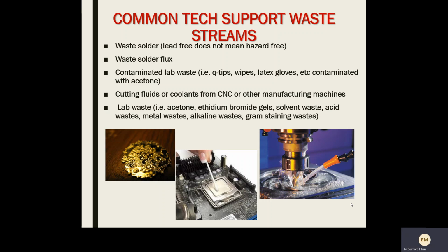Some common waste streams seen in labs or tech support industries can include solder flux and solder dross. Many facilities will point to the fact that the solder wire that they use is lead-free. However, you should note that this doesn't necessarily mean that it's hazard-free. It could contain other toxic metals that could cause it to become regulated.